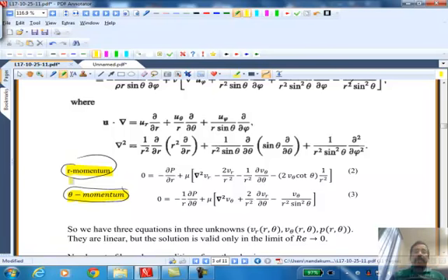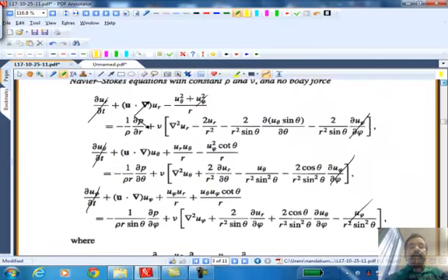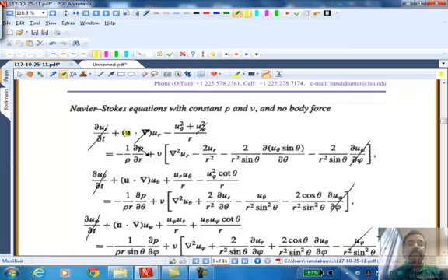Okay. But the r momentum equation, on the left hand side we have 0. Why? Because the flow is steady and it is low Reynolds number. So all the inertial terms are not identically 0. If you go back and analyze this, for example, in the r momentum equation, you have u dot del ur. And here you have u theta squared divided by r. That's not 0. But we are going to ignore that because it is small. It gets multiplied by Reynolds number.